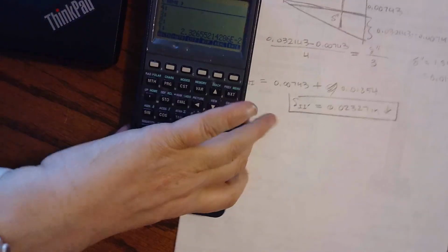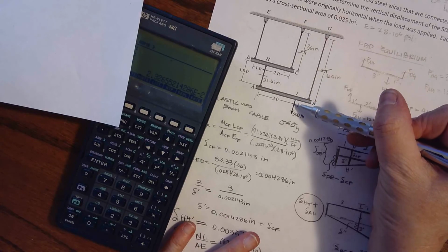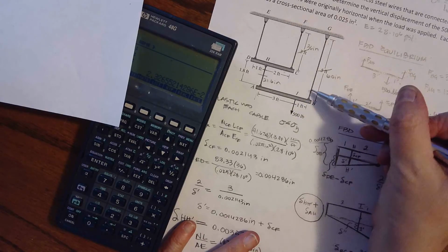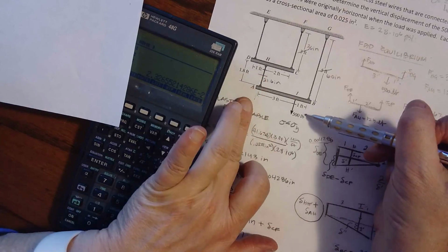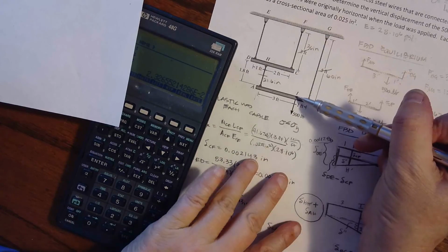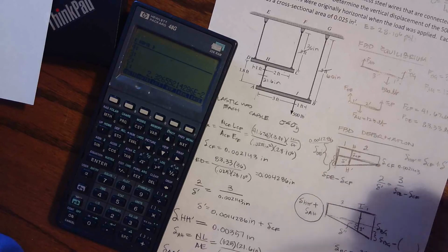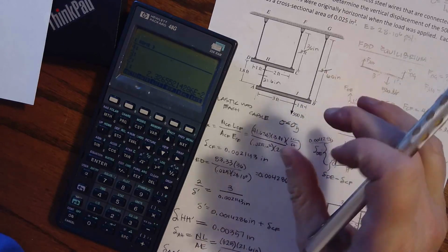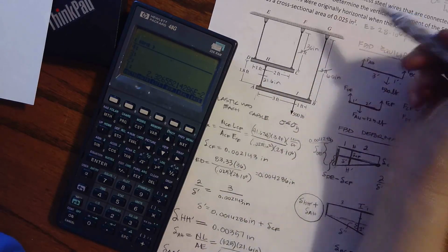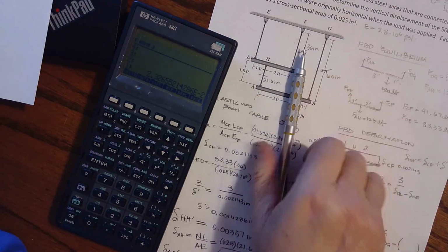Let's go back through our mess here. What does that mean? It means as I loaded this system, this is going to drop down because I'm stretching these cables, so it's going to come wonky down. We're applying a force here, so these are also coming down. So when I load this, this point I is going to go down 0.02327 inches, which is very small. We wouldn't be able to notice it. It's very small strains. This is a very good example of an exam question, except we might have springs in here and some shear blocks, so we can have you working with shear as well.